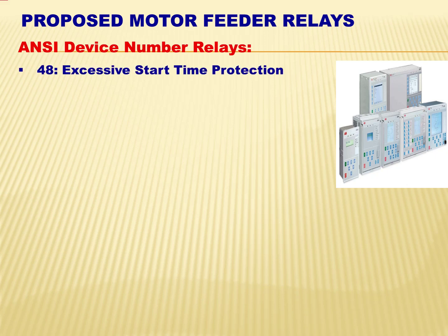The first one, we have here relay 48 or the excessive start time protection. This relay 48 protects the motor from prolonged startup procedures, thus supplementing the overload protection.